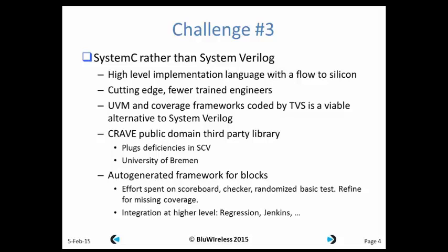And we've been able to integrate all of this from the very top, so the whole C2S generation down, into regression suites, and we're using tools like Jenkins. If any of you are familiar with Jenkins, it is a system for automated test and test management, allows us to generate a complete system, run through the whole regression automatically and control that in parameterized ways.